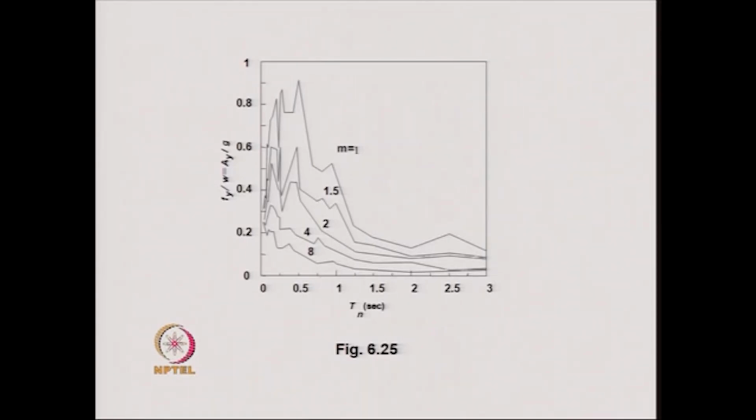For the case of multi degree of freedom system, we will see how we can extend this and use these inelastic acceleration response spectra for the design for an expected value of the ductility factor of 2. So, the use of inelastic response spectrum is the design of a particular structure for an expected value of the ductility factor.